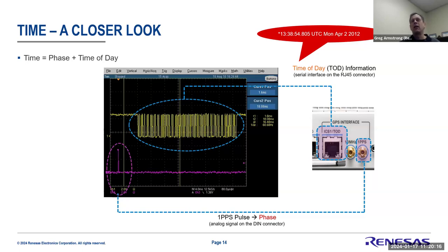And so typically, a lot of people don't use 1 PPS as a distribution means. You usually use other mechanisms to distribute phase and time, such as protocols, which will use a frequency component to try to get that sub-nanosecond component, and also maybe deliver that timing information more than once a second, or have something else that can help stabilize the clock so that even if you're only getting an update once a second, it makes it easier to recover the frequency component and get that precision in how many events you can make sure happen exactly within that 1 second.